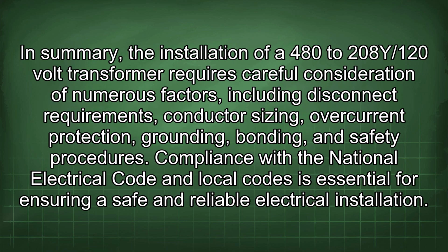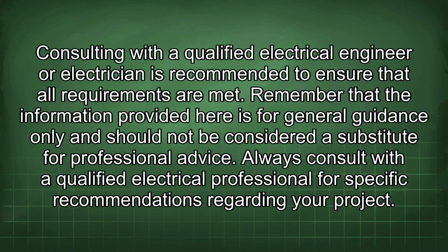In summary, the installation of a 480 to 208Y/120 volt transformer requires careful consideration of numerous factors, including disconnect requirements, conductor sizing, overcurrent protection, grounding, bonding, and safety procedures. Compliance with the National Electrical Code and local codes is essential for ensuring a safe and reliable electrical installation. Consulting with a qualified electrical engineer or electrician is recommended to ensure that all requirements are met.